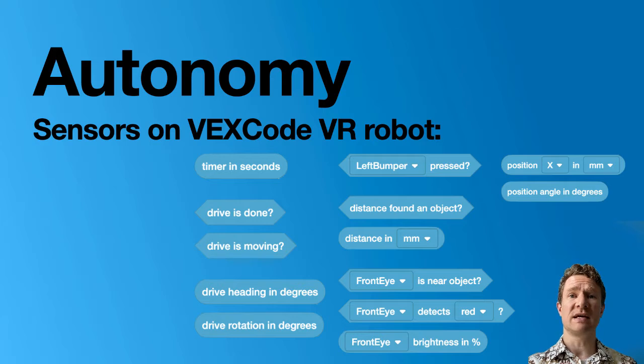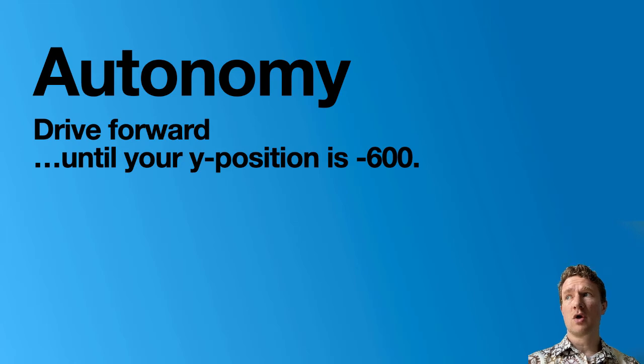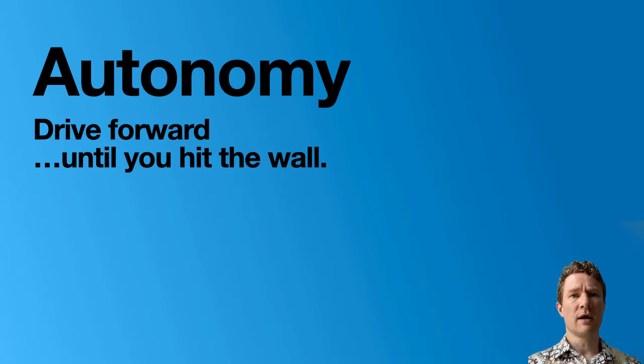And so all of these things allow you to go back to these structures where you can drive until a condition is true. Drive forward until you are 500 millimeters from the wall. Drive forward until your Y position is negative 600 millimeters, for example, or drive forward until you have hit the wall. So let's take a look at all of these in VEXcode VR so we can get an idea of how to use these ourselves.